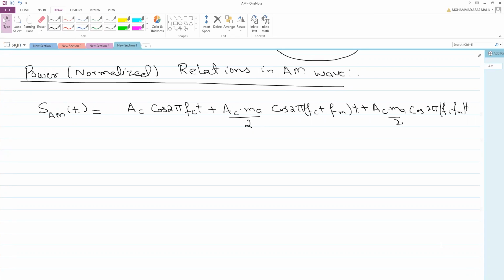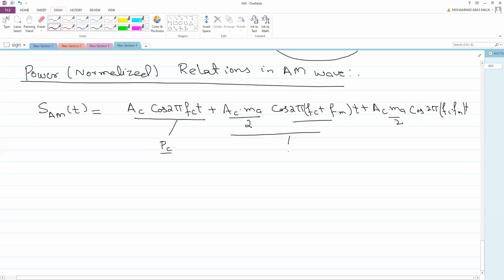Now, this one is your carrier signal. That means in the modulated wave, you will get the carrier. And this is just a wastage of power because we don't need the carrier. We need the message signal, that is in terms of this envelope, this and this one. So then you have one sideband that's called the upper sideband, and then you have the lower sideband.